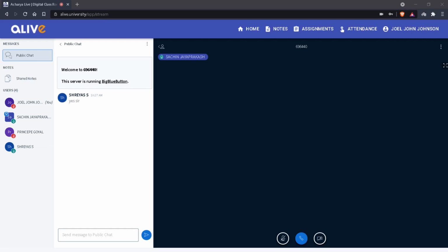As this was a very small diagram, the radius was 10, the maximum value it could afford. And similarly here also, by default it is 10. If you want to go a little less than 10 or more than 10, in this particular sketch it's not possible. So what you can do is do it after doing the 3D part.